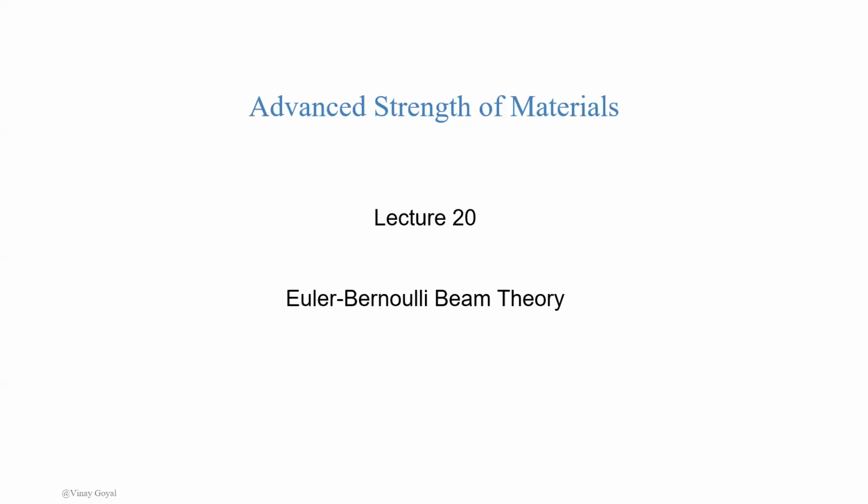So, for example, if you look at this classroom, you will see there are chairs here that are supported by something that looks like beams. They're long, tubular. You can see it there. But using three-dimensional finite element modeling to simulate a tube that's long and has a uniform cross-section is not very efficient. You can then use beams instead to represent the behavior of, say, a chair's supports, rather using simplified methods.